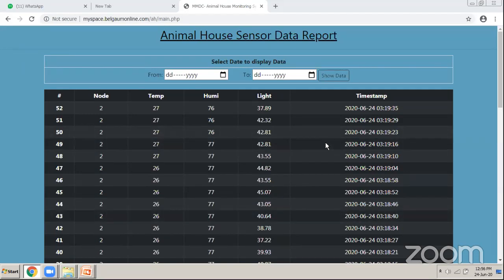Okay, so what I was telling is, to rotate a wheel for a robot, you need DC motors. DC motors have two terminals, positive and negative, or you can say A and B. There is nothing called positive and negative in a DC motor. When you apply the positive of the power supply to one of the terminals and negative to the other terminal, it will start rotating clockwise, let us say.